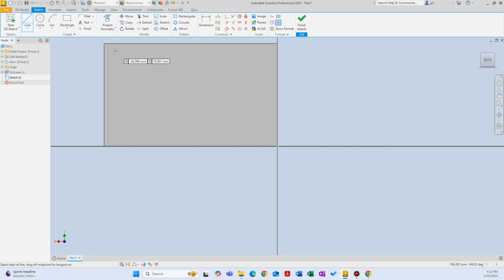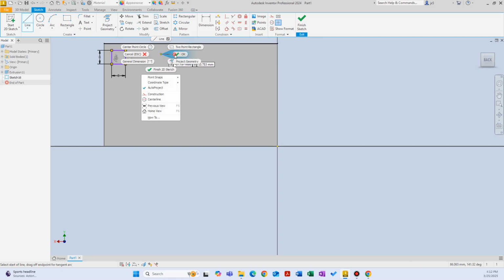So let's create a line here. I'm just selecting a random spot at this point. Again, we're not going into much detail. We're going to design these products with more detail later. So let's make this 8 millimeters, and then 8 millimeters here. See, it already recognized the beginning point of the first line, and I didn't have to enter 8 millimeters there.